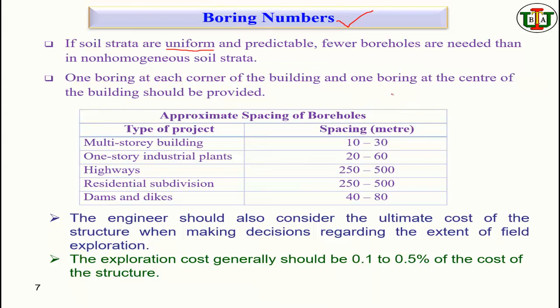But if it is non-uniform, non-homogeneous soil, you need to do more. For uniform soil, you can do fewer boreholes, and for non-homogeneous, you need to go for more. They are saying that one boring at each corner of the building and one boring at the center of the building should be provided. So the corner and the center must be covered, and after that you can decide the spacing.